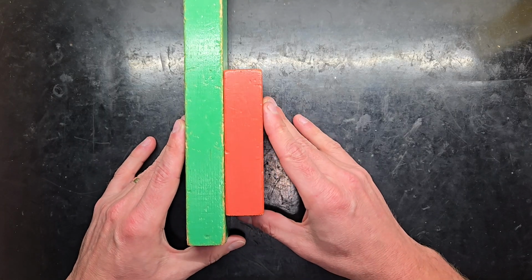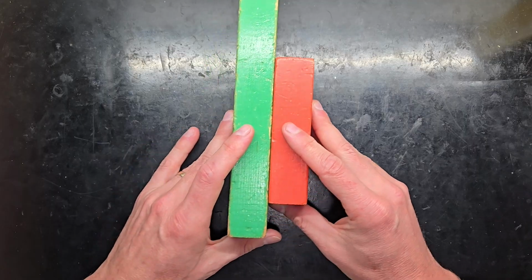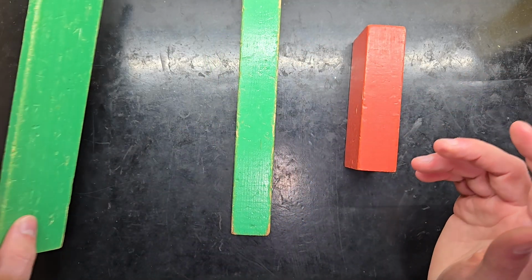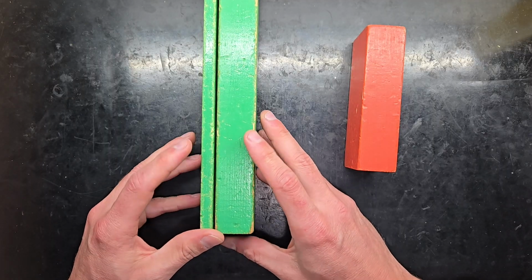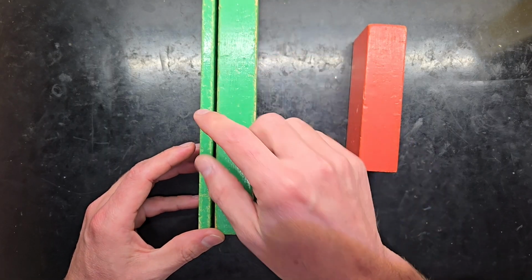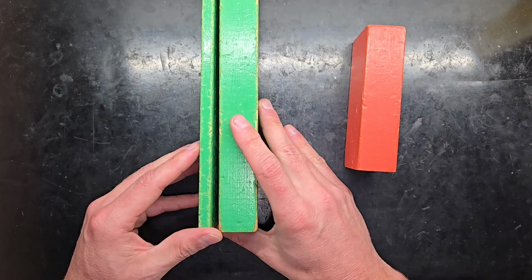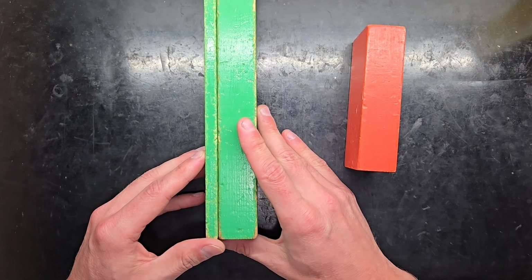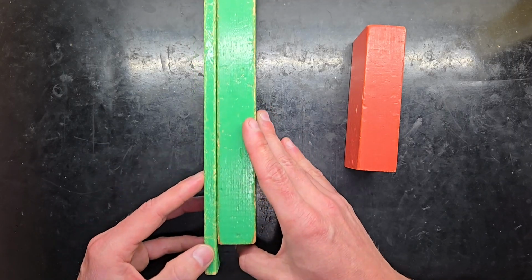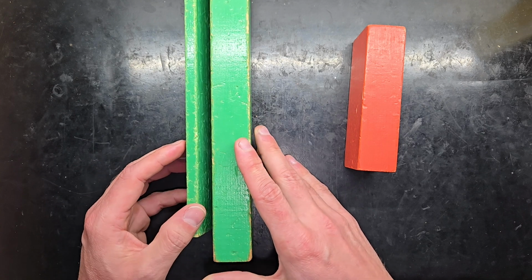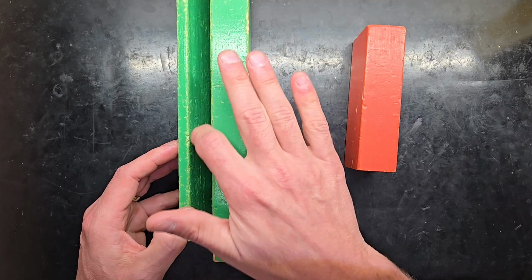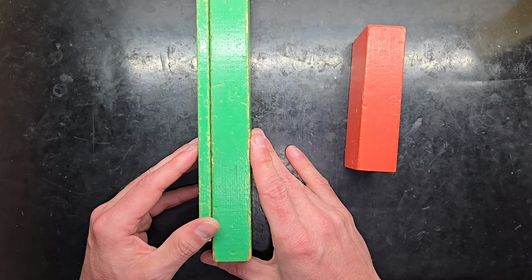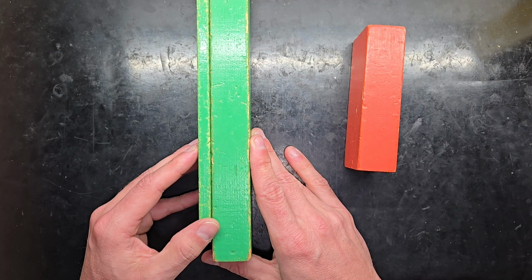Abrasive wear can take place between either dissimilar metals or dissimilar materials or similar materials. You need a third party in the middle, and common third parties would be sand and dirt. So as you have the relative motion between the two bodies, the sand or dirt is what's creating high stresses on the surface contacts between the two and causing material to be removed.